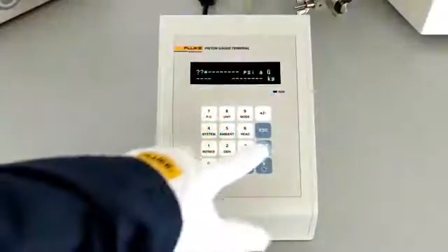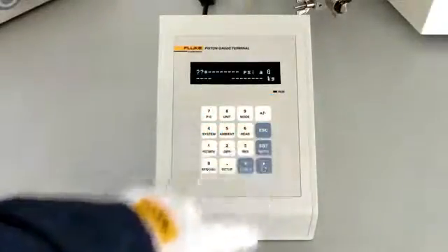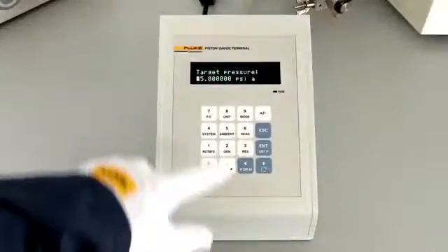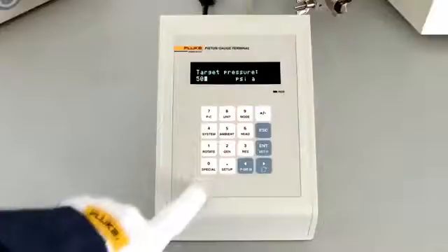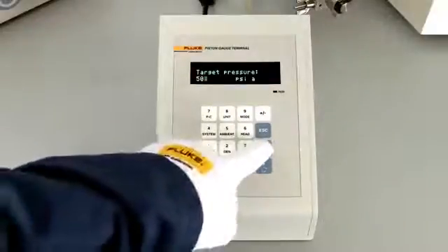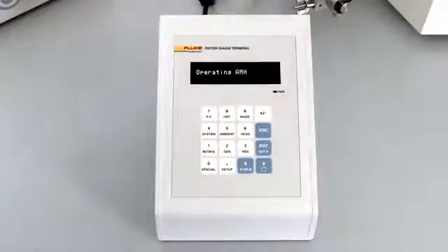The first extreme is to measure each variable that impacts the pressure and perform a full calculation of the fundamental pressure equation. This is the approach used on high-end piston gauges, like the Fluke Calibration PG7000 series. By using this approach, with the right equipment, it is feasible for one to get the lowest uncertainties possible.